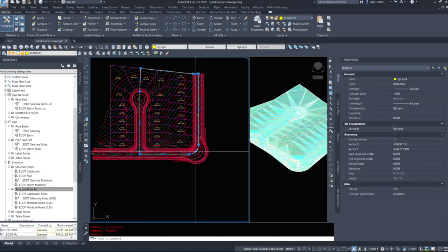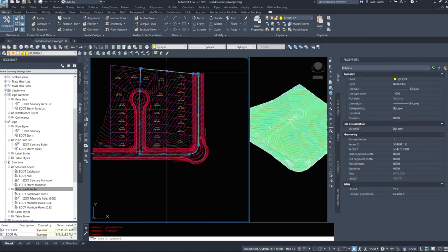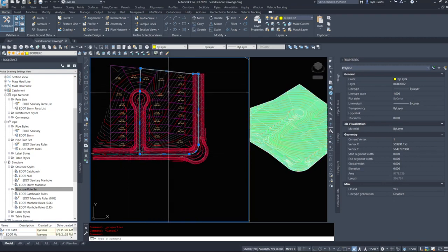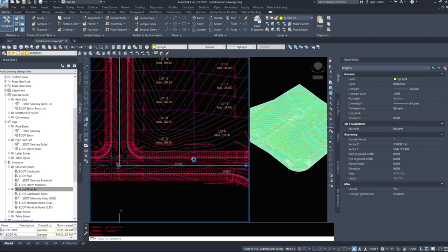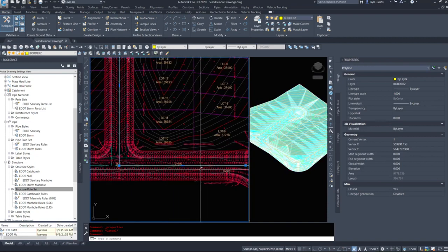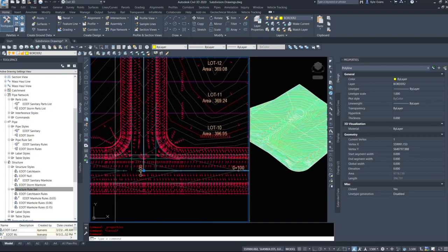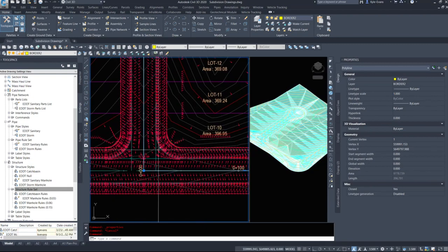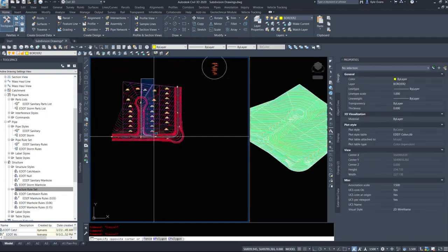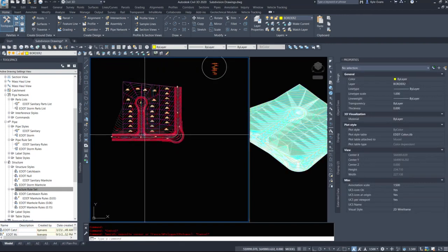We have a catch basin here, we have a catch basin here. Do we want to add a catch basin, where there will be a swale at the back of these lots? Do we want to add a catch basin here? Can we add one? For sure we can add one. However, in this case we would need another manhole. As we have a catch basin here, we can additionally add one on this side to cut the flow off. And we could take this area that's in blue here and funnel it into this catch basin here.